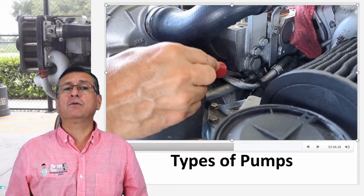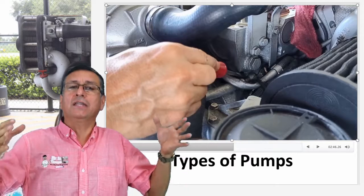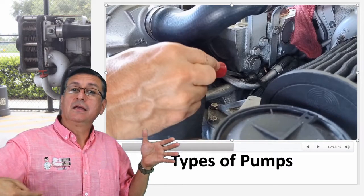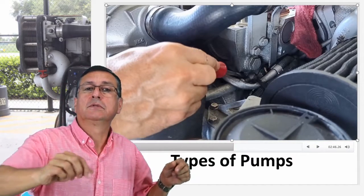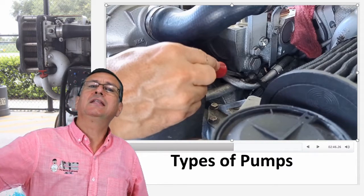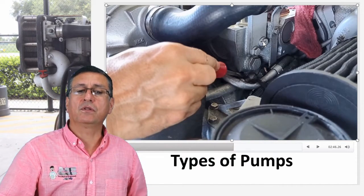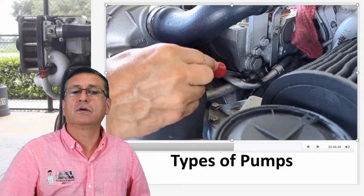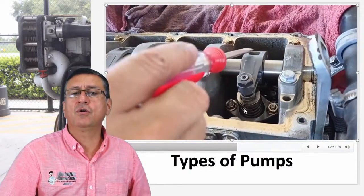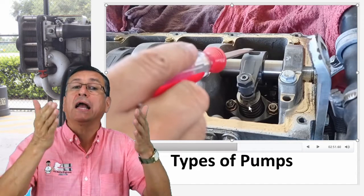The manifold in that particular engine is cast internally in the head. The head internally has two cavities. One cavity is for supply and the other cavity for return. Okay, in this particular case, the fuel enters here and enters the head, the intake manifold. The manifold that receives the fuel, the intake manifold or supply manifold. Okay, and from the manifold, the fuel enters each injector. Those are the injectors. In this particular engine, the injectors are mechanical injectors.